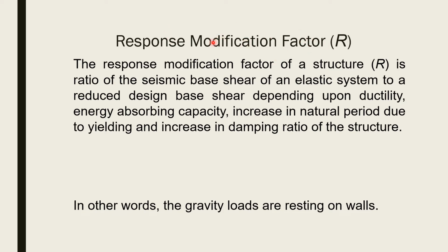Depending upon what? Depending upon ductility, the energy absorbing capacity of your structure, increase in natural time period due to yielding, and increase in damping ratio of the structure. So depending upon these factors, the response modification factor works. The actual base shear is 800, but due to response modification, that base shear can be reduced to 200 kilonewton. So that is a very important response modification factor.